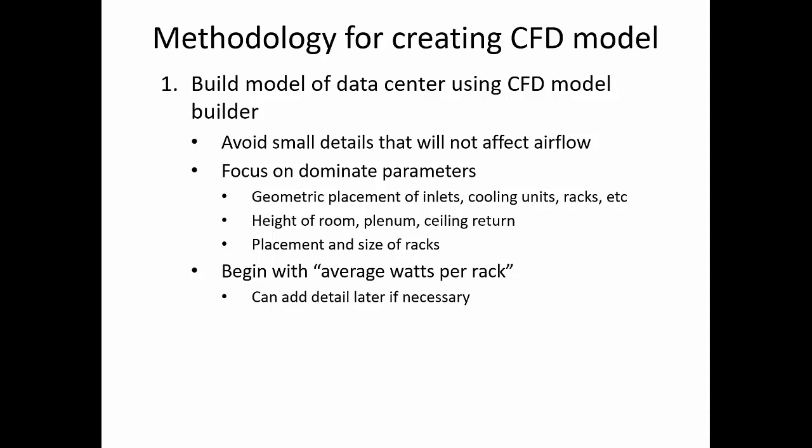The other thing about average watts is oftentimes we don't know more than this, right? Because unless you go in and do a physical inventory, you don't know what the distribution is. And even if you do physical inventory, it's difficult sometimes to determine what the allocation of wattage is in the rack because you have to instrument each of the servers. You can guess if you like. Some providers like to say, well, it's 60% of total nameplate. So you take the worst case condition of the server and then you multiply it times 60% and you use that. That's still a guess.